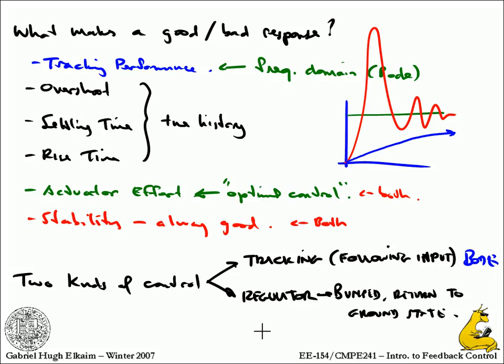Oh, really? Oh, direction? It's 2,000 feet actually at flight level 18 and above, but lower down they have reduced it, but it's never less than 1,000 feet. Usually, if you're flying north, it's always 33,000. If you're flying south, it's 34,000. If I'm not mistaken, eastbound it's odd altitudes plus 500, and westbound it's even altitudes plus 500. That's VFR, yeah, for VFR.